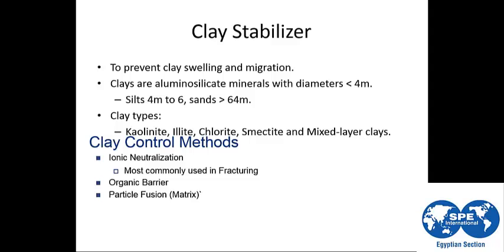This means that these ions in the clay stabilizers will attach themselves to the surface of the clay ions, or clay molecules, or clay particles. So this will result in a barrier between the water, or the water-based frac fluid, and the surface of the clay. This will prevent direct contact between both of them. In this way, you are stabilizing the clay and preventing swelling.